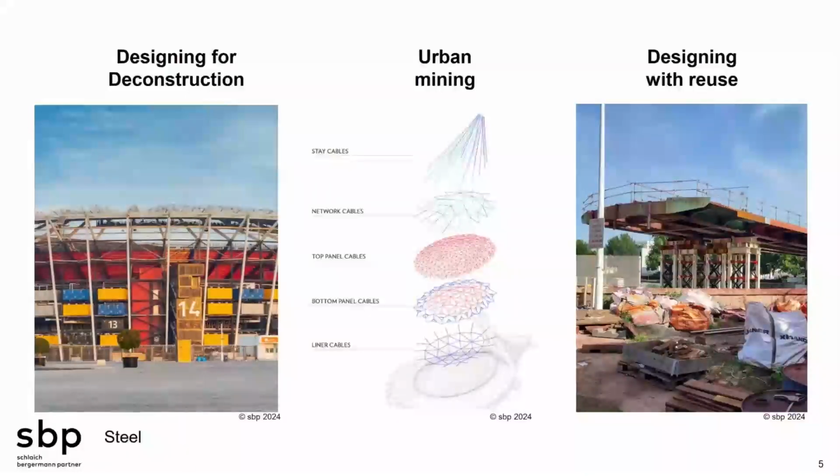And it's really because it follows quite simple methods: designing a simple repetitive frame, selecting generalized loading for your structure, using a modular and rationalized approach, which allows for replacement and rearranging of elements within the frame, and thinking about transportability requirements. So limiting the maximum size of your design elements, limiting the weight of individual elements, and thinking in the future about a tracking strategy.